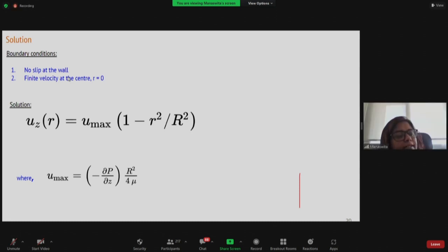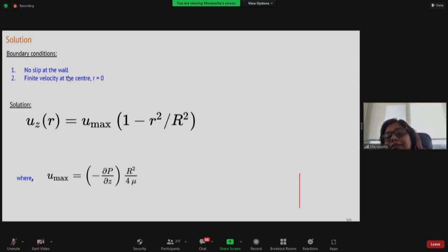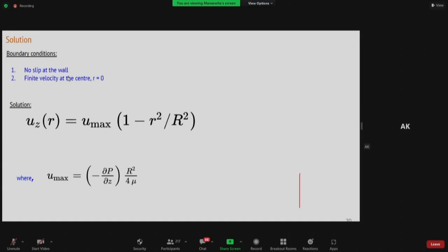In general, at the outlet you have to give a boundary condition, right? Yes. Generally, it is mentioned that at the inlet you prescribe the velocity, and at the outlet you prescribe the pressure. That is the most general boundary condition. I was trying to figure out the answer for that. Why is it so? Why can't we prescribe the pressure also at the inlet, like velocity?